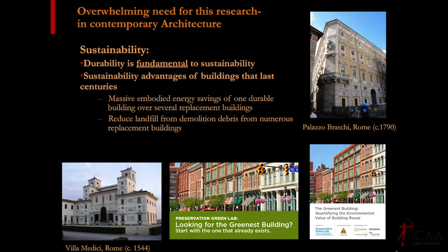They had a whole team, including contractors and architects, that studied case studies of buildings, reusing a building and making it as energy efficient as they could, which was never as good as a brand new building, and looked at all the life cycle cost and embodied energy cost, and which is overall better for the environment. Over 95% of the time, reusing the existing building, even though you didn't bring it to as high a standard of energy efficiency, was better overall for the planet than knocking it down and building a new ultra-high efficiency building. So it's an interesting study and a free download.